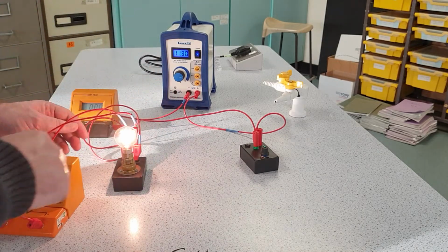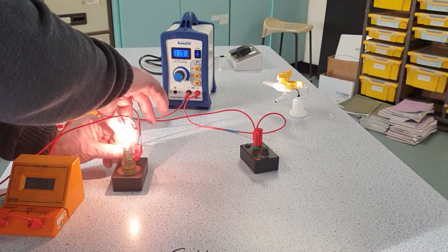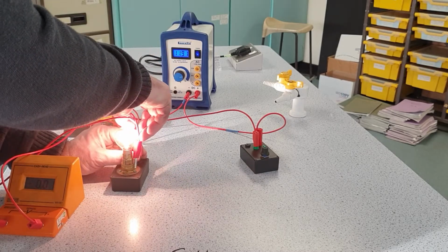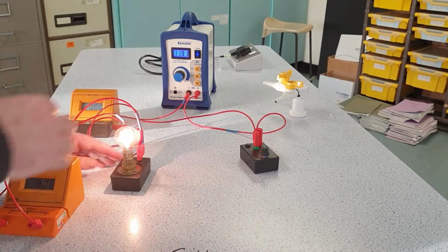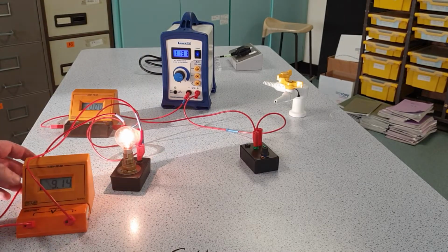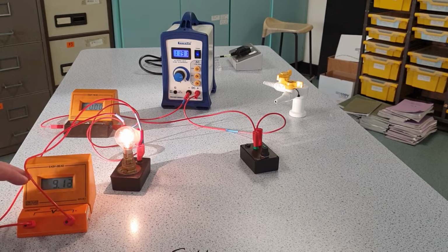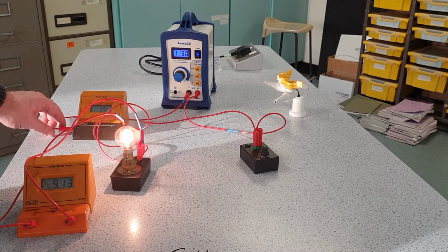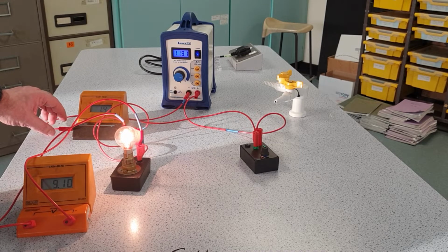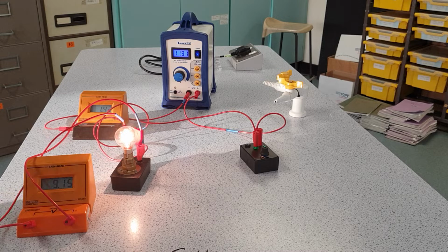So there we go. I've got a negative reading on the voltmeter. Now I can cure that just by swapping the leads around. There we go. I've got a positive value now on the voltmeter. So it's reading 9.1 volts. The ammeter, strangely, is not reading anything, which probably indicates a loose wire connecting there. So I've just adjusted that. The ammeter is now reading 1.4 amps.